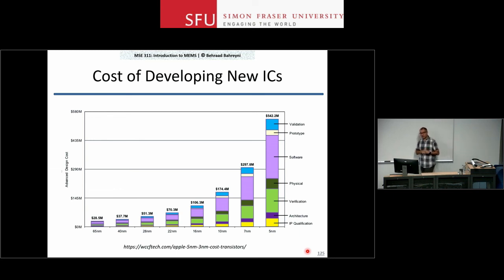Sometimes in very rare cases, if the chip complexity is not too large, you can actually do a little bit of post-fabrication manipulation. You cannot do that for digital stuff. There's just way too many components there. But for analog chips and MEMS chips, it might be worth it if it is a high-value component. But in most cases, you're just trying to avoid any such manipulation. So that's that for the lithography step.